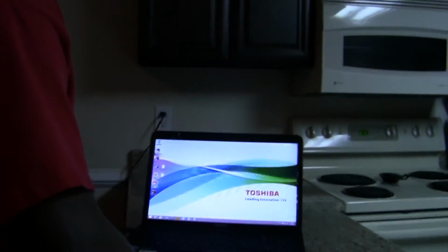The tasking was to do an assembly language program and MPLab simulation exercise, which did operations in addition, subtraction, the AND logic, the inclusive OR logic, and the exclusive OR logic. We're going to start by logging into MPLab.